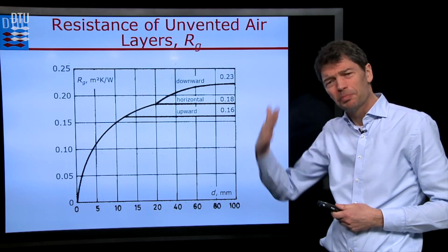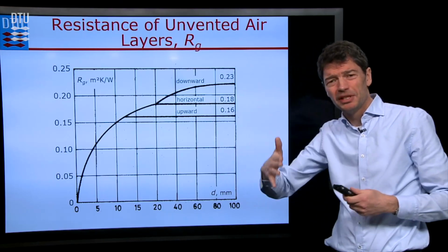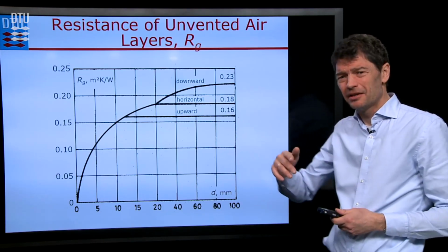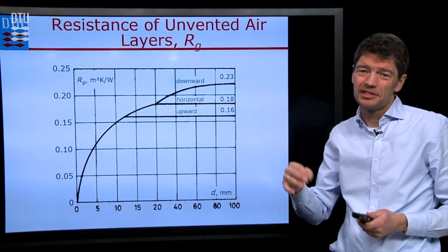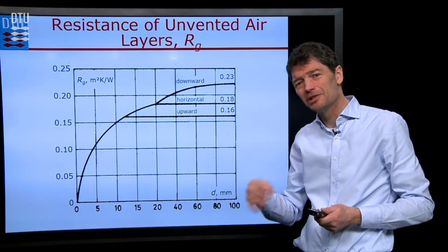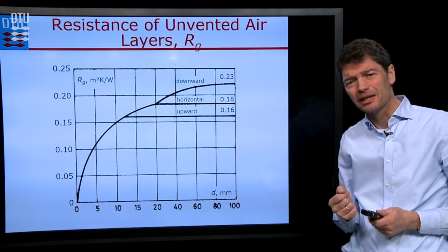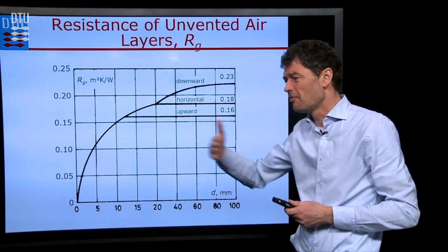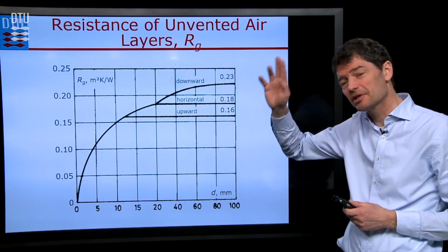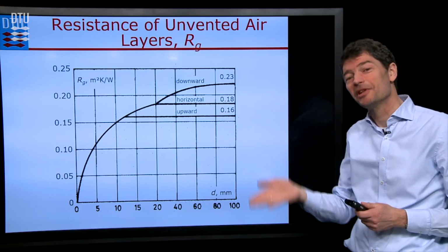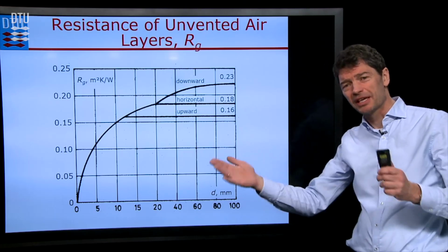Let's consider one small extra topic in this subject. There could be a layer inside of a wall, which could be an air layer. In an air layer we have to consider both convection and radiation, but very often in standard calculations we can simplify that by using standard thermal resistances. That depends on whether we have a horizontal or vertical heat flow, and if it's vertical, whether it goes up or down. And then it depends on the thickness of the cavity.